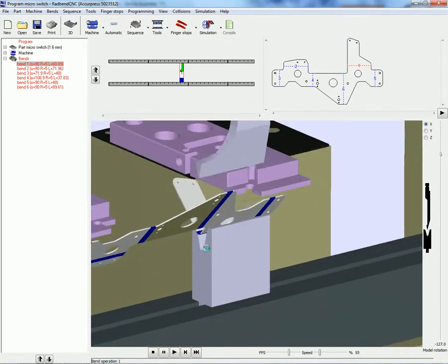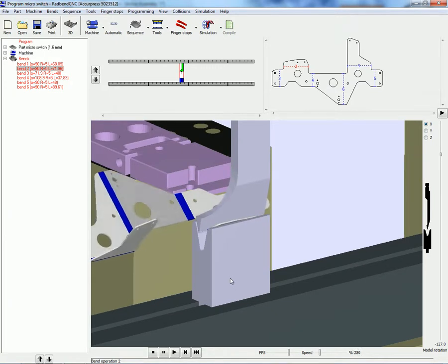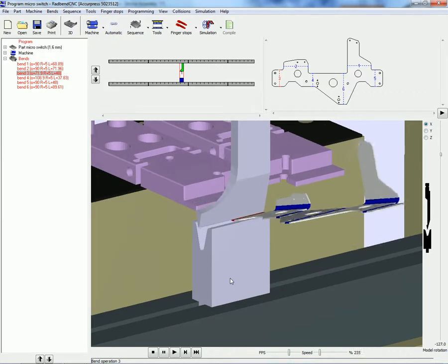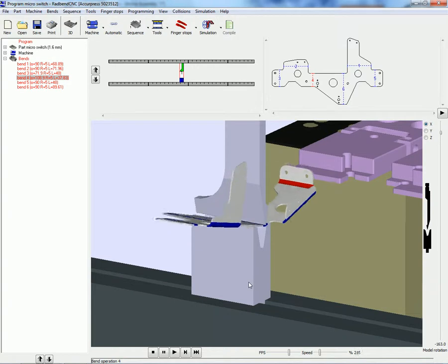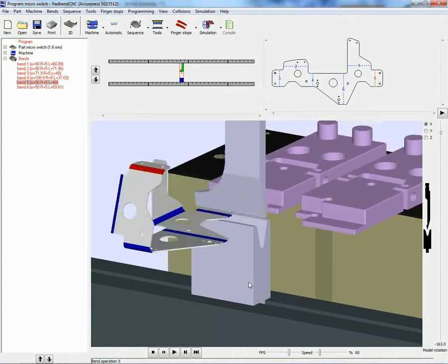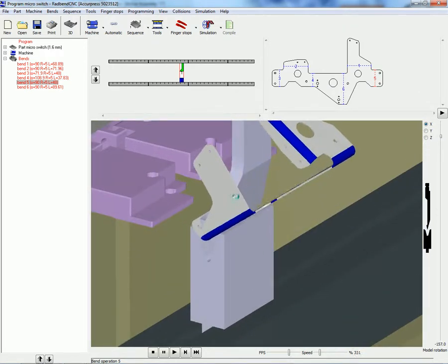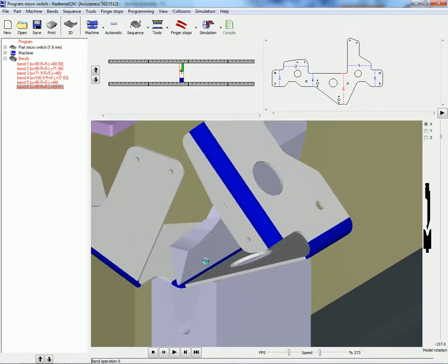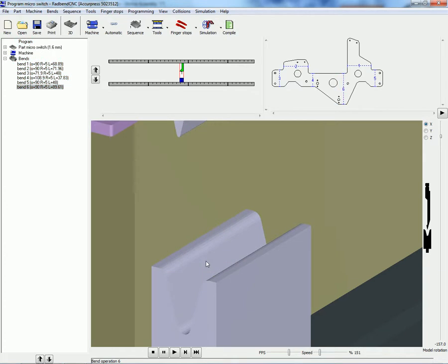And again, here it's chosen quite a wide V, so I get the radius that I required, which was a 5 mm design radius on the 1.6 material. And if you watch this last bend closely, you'll watch the overbend into the spring back angle.